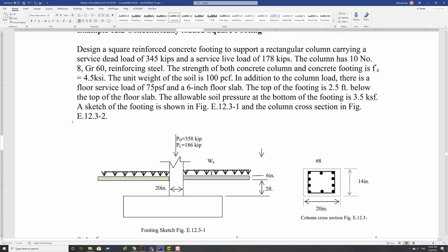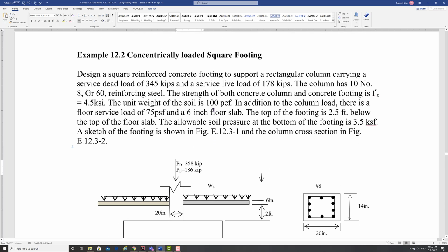Remember you had these first floor loads that we were not using? Now they become important because you had to transfer that here. It will be subtracting from your gross value to make a net value, right? And so that's what we have. Then I also gave you the unit weight of the soil because you need to add this weight. Now you can add all this. Normally we ignore this column and we say all this is weight of soil. Okay.